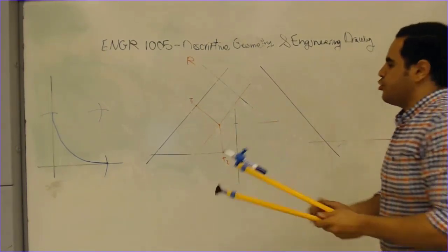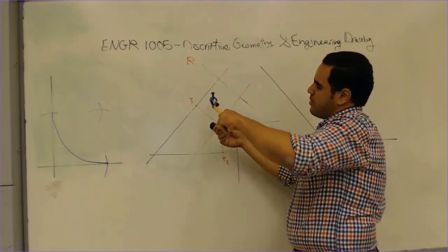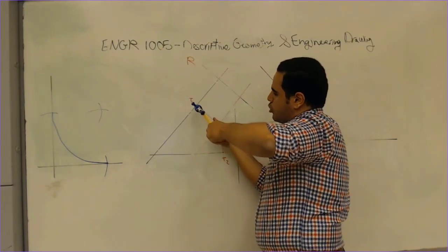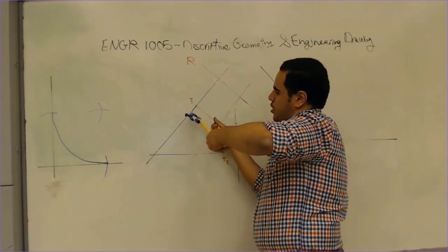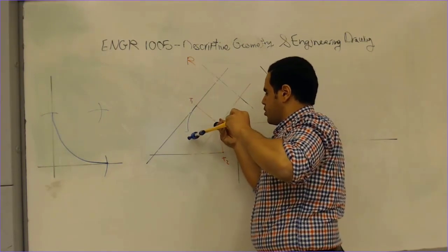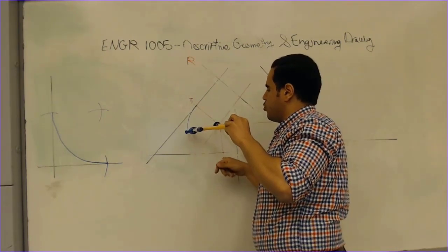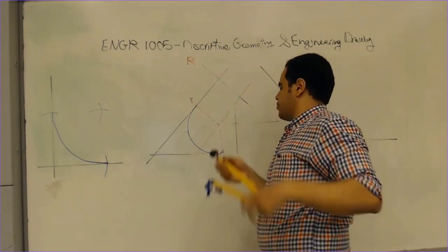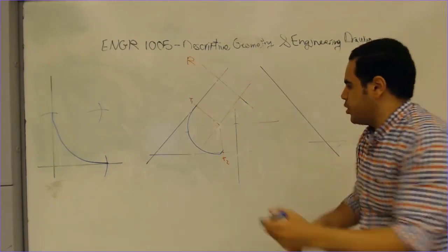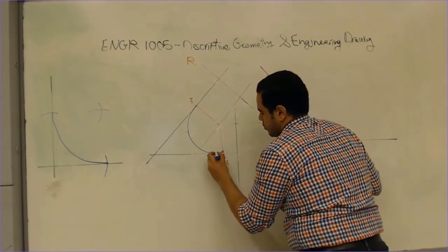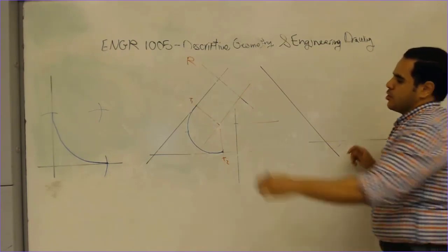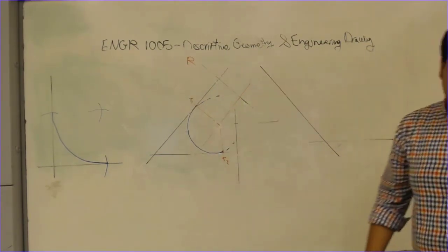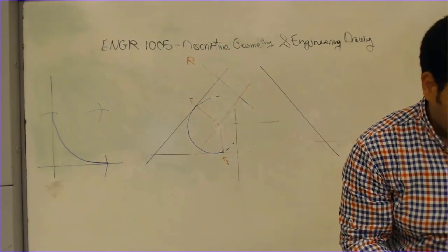Because I don't want you to draw the whole circle or some extra arc of the arc we want to draw. Just want you to draw from this start and end it here. Okay? So this is going to be your fillet. Okay? We don't want you to draw some extra lines here and there. Just stop at the first and second point of tangencies.